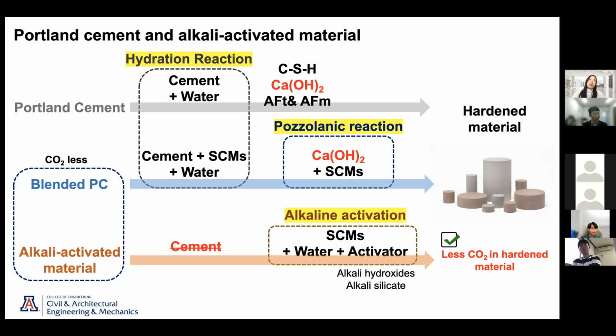In blended PC, where SCMs are added to cement, SCMs will react chemically with water. Also, the pozzolanic reaction, which is a chemical reaction with hydrated cement, leads to additional strength-bearing phases and densifies the microstructure of cement. In alkali activated material, we use only SCMs, without cement, which emits CO2. SCMs are activated using alkali hydroxide and alkali silicates, and produce hardened material with less CO2.